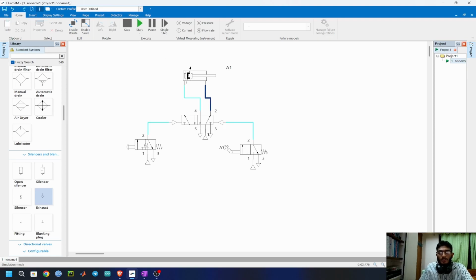Okay. So if I press this button, the cylinder will extend. It will go to A1. The A1 will trip this lever. The left side of this DCV will actuate. It will signal the right side of the 5x2 DCV. Then the cylinder will retract again. Go. See? Let me show you again. As I explained. So this problem is solved.